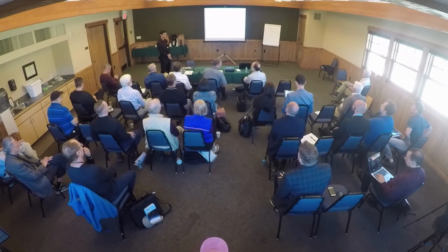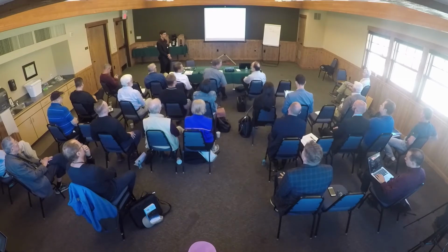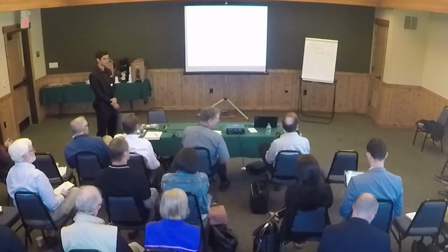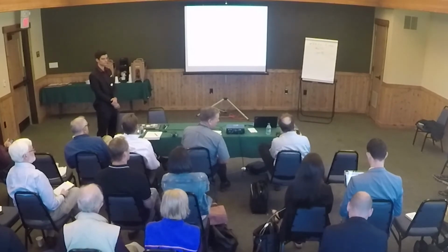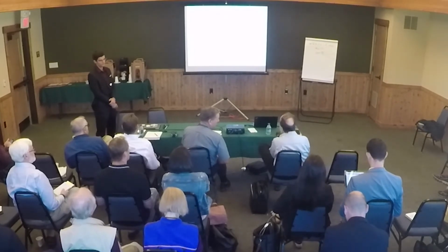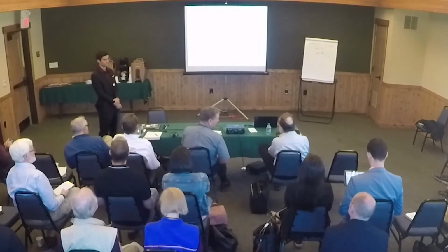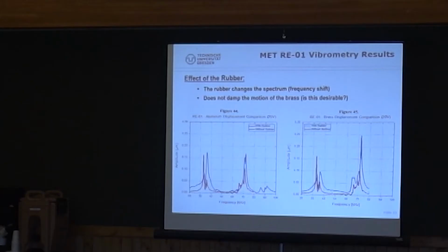Now, people were saying that the rubber has a modulus of elasticity many orders of magnitude less than metal. So according to what people were saying, that the rubber was decoupling, when you have the rubber you should have a lower frequency. But look at what the experiments are showing. When you have the rubber, you have a higher resonant frequency.